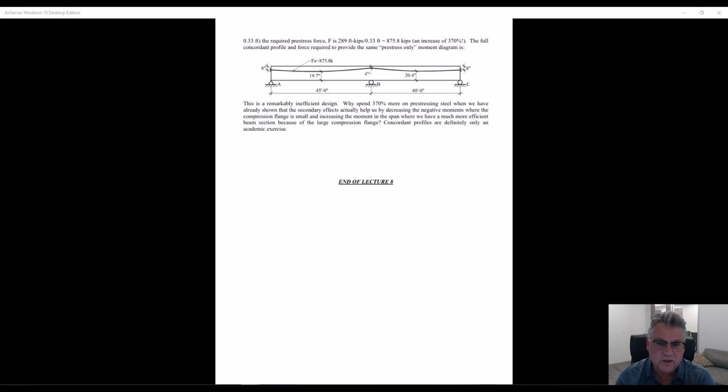This isn't particularly difficult either, but the real trick, and where my focus will be on your second exam and what I want you to really leave this class understanding, is that the demand changes in post-tension concrete. In indeterminate members, which we always have, you're probably never going to, in your entire 40-something year career, design a statically determinate post-tension member. They're always poured in place, cast in place, multiple spans, and indeterminate.